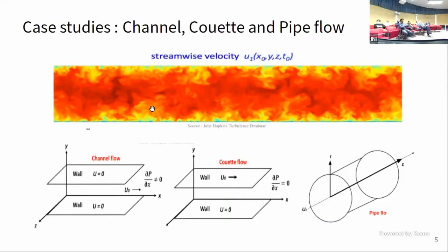So you can appreciate the number of scales that turbulence has, and it is a very chaotic phenomenon, and hence it has been quite a challenge to develop turbulence models for this very same regime. But if I take the time average, you won't see all those scales, and you just have a nicely behaved mean. But then you have to talk about the closure as well. That's why the modeling is actually quite complicated.